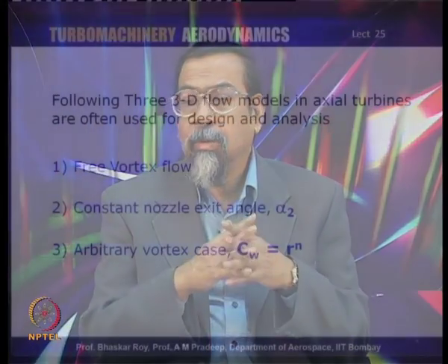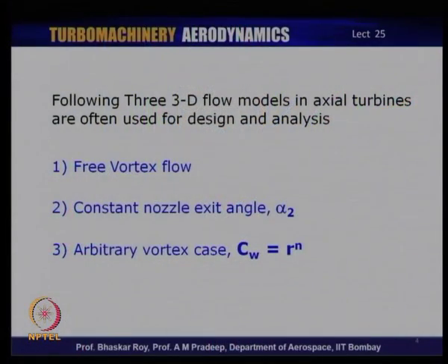So, having invoked the simple radial equilibrium equation, the next thing to do is try to find out what are the 3D models, or as I mentioned, more of pseudo 3D flow models, which need to be invoked for design and then immediate post design analysis.